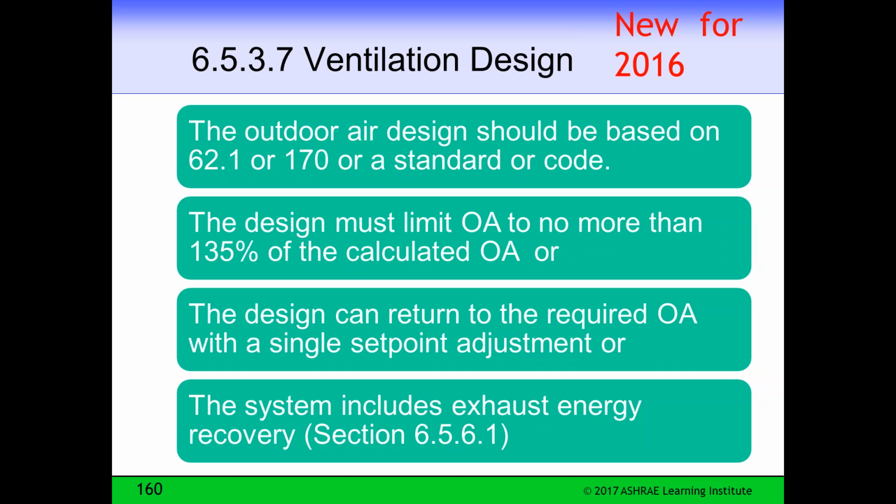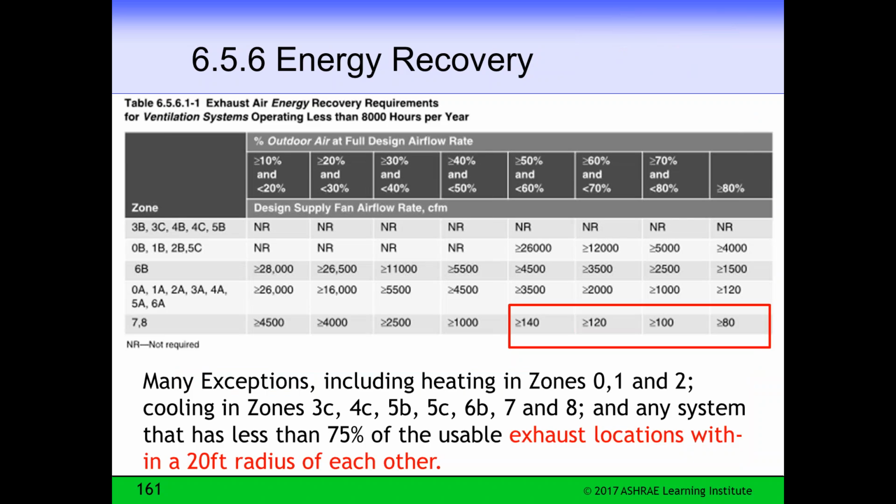Or if you're using exhaust energy recovery, you need a certain amount of relief air for the exhaust energy recovery to work properly, and you're getting work from that exhaust air, so we'll let you increase it some.